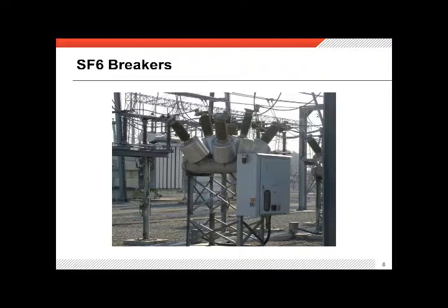You've got disconnect switches on either side of the breakers, although you can't really see them in this picture. But you have 3 different poles. You can see the outside phase right here, and the interrupter is inside that cylinder. You have 2 bushings, and there's cowlings under which you'll find the current transformers.